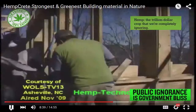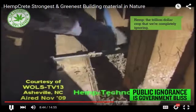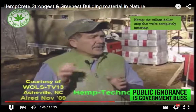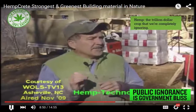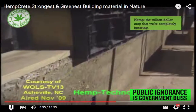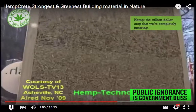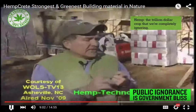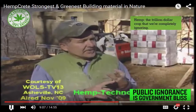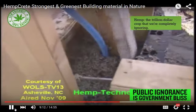Before you make any jokes about workers getting high on the job, builders quickly point out that hemp is not marijuana. The industrial hemp plant is a cousin of the marijuana plant, but it has very little, 0.03% THC. You can't get high on this. Madeira says Hempcrete has many health and economic benefits. The material allows air and moisture to circulate, preventing the buildup of mold, mildew, and other issues. With this product, you'll have no termites, no dry rot, no moisture issues, because the air is constantly moving in and out.